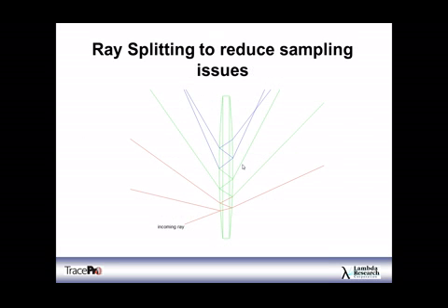So if we look at this graphically, here we have a ray incoming to this particular lens. And you can see the splitting going on as it reflects and transmits through this particular lens. This is where you would get ghosting, for instance, of this ray as it's coming through. And you can see that we're just going to keep ray splitting forever until it drops below the flux threshold or some other intercept that we set up in the ray trace options.